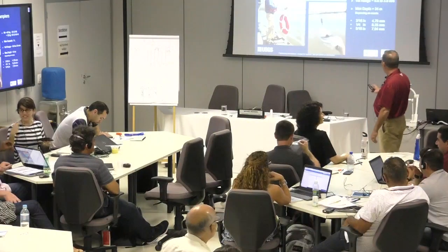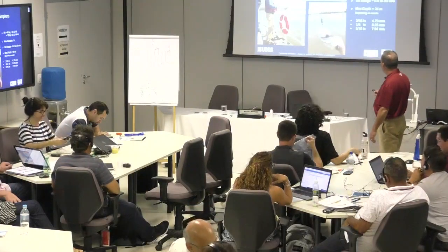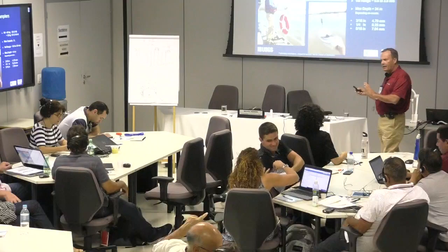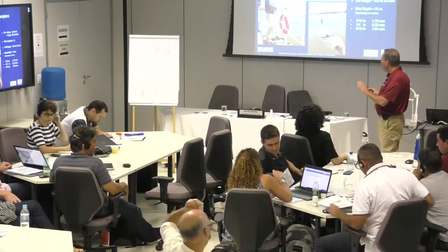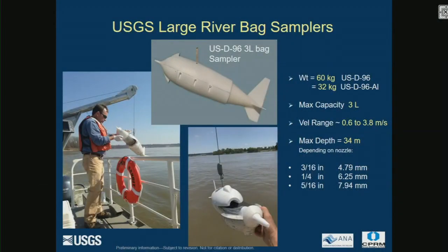So I'll just point out on this photo here where this boom is set up on the back. If you're doing this type of work, regardless of how you build these booms, make sure they're supported, and you can reach the sampler to unload the bottles or the bags, and that the boat is balanced. And so that's a major thing that you want to look at.